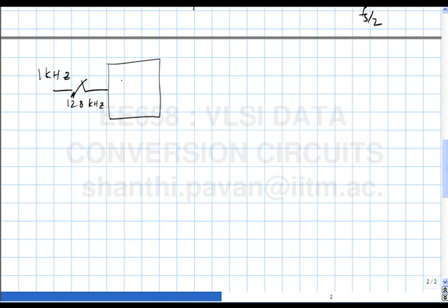I pass this through a quantizer, say a 5-bit quantizer, and the amplitude is 1 volt for the sine wave, and the quantizer range is 2 volts. So that basically means that the sine wave is exactly fitting in the quantizer range. The quantizer is not getting overloaded, right?